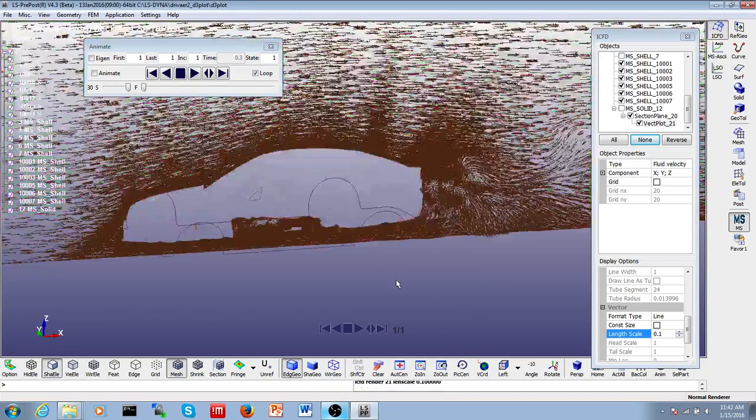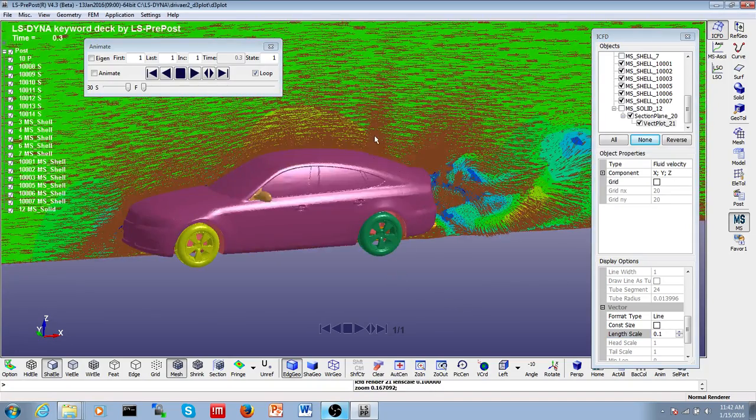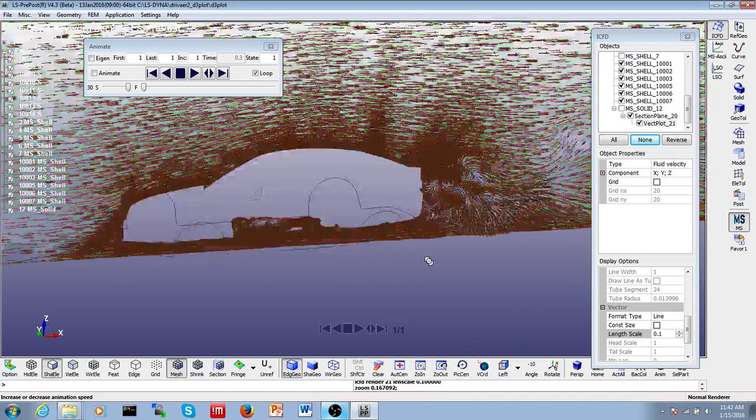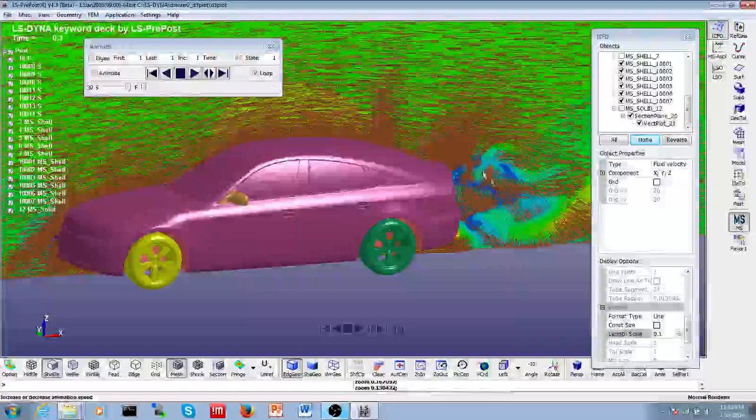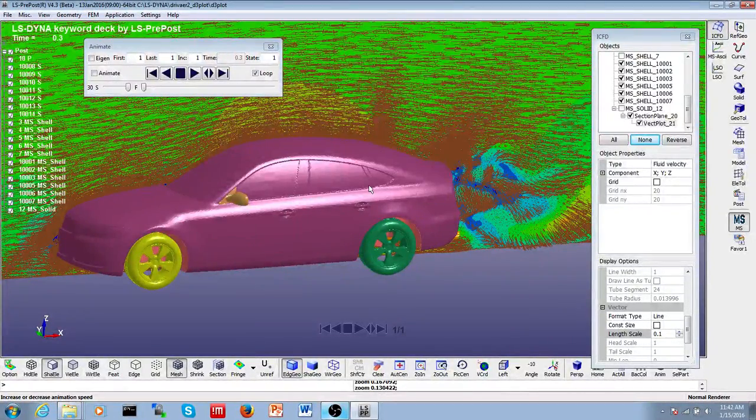The reason being is that our mesh is unstructured and it plots one vector at every node, so obviously here we have a lot and we don't have many here, but overall it's hard to see what's going on, except that here we have something that's moving. What if I want to extract a velocity profile, for instance?